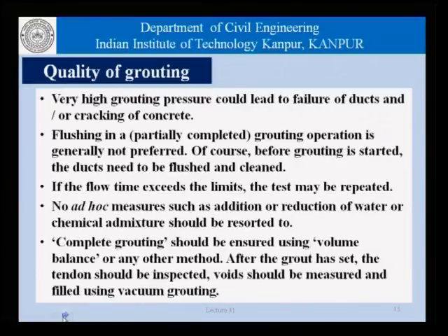So, basically there is very little that we can do once we are grouting a post tension pre-stressed concrete tendon. We do not know if all the void, if all the space in the duct which was supposed to be occupied by the grout has been occupied by the grout, other than by doing some kind of volume balance or carrying out non-destructive tests, which could be carried out while the grouting operation is being carried on or after the grout has set, and then we look for pockets of air.